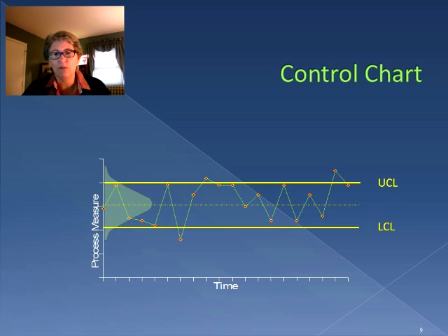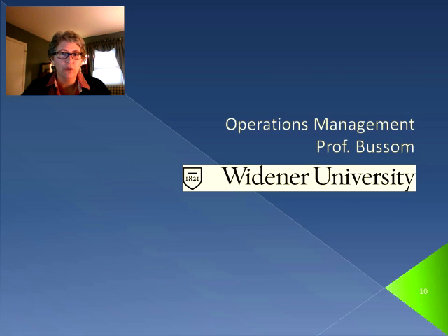And we can see that most of that variation actually falls inside those control limits, so that would be natural variation. But we also have 3 points that fall outside of these control limits. This is what we would look for in terms of assignable variation, because it is now beyond 3 standard deviations away from the mean. It is most likely due to an external cause. So that's generally what we do with control charts.